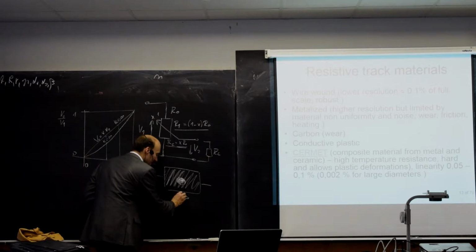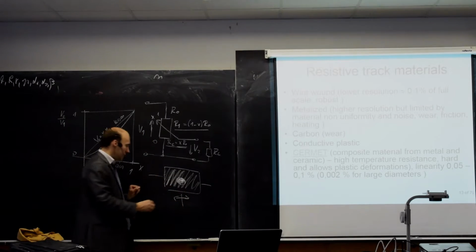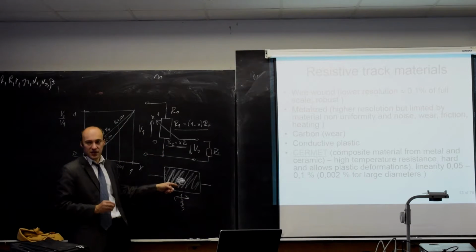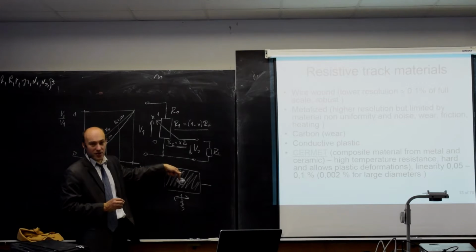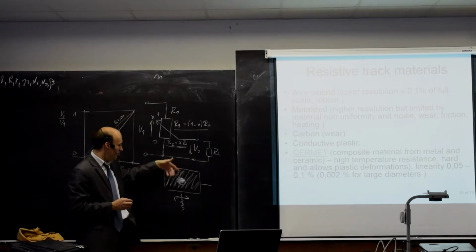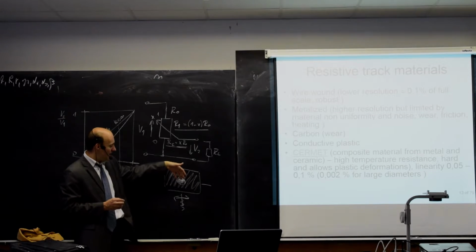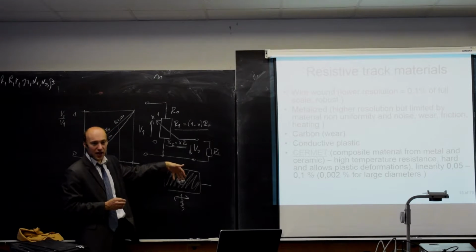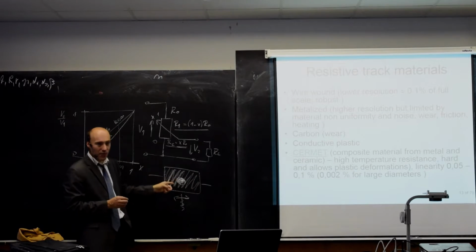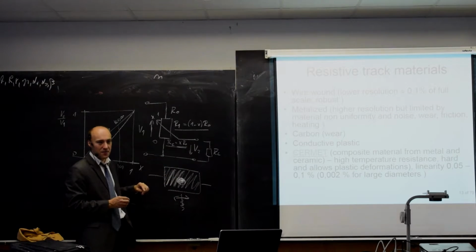But for example, if there will be vibrations superimposed on some constant position, then it will damage this layer at one spot, and then you will have, let's call it, a blind spot, damaged at this point. So it will work in the whole range, but at one point you will have a discontinuity.